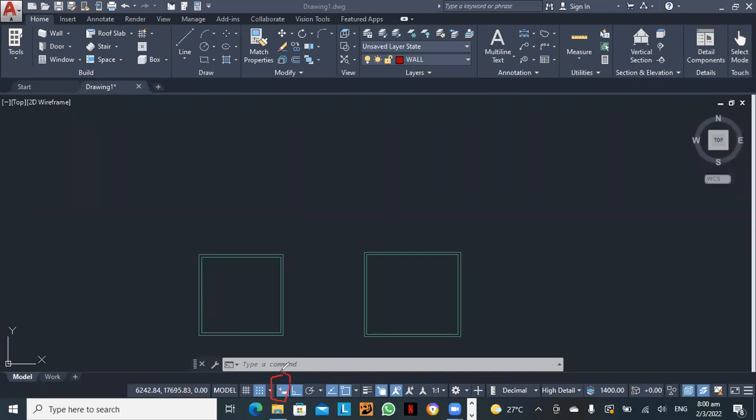this is active, you're able to simply enter the start point and enter the X and the Y value. All right. The dynamic input allows the user to enter the X and the Y value for a rectangle. See, for example, this rectangle with dynamic input, you're able to enter the X and the Y value here. The X value is normally the horizontal one. The value that goes across is normally the X value.